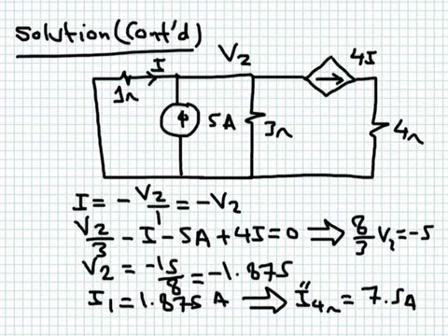Okay, we repeat the circuit analysis. Now we get rid of the voltage source, we shorted it out. We keep the current source. Again, this circuit has only one node. This is one node here. These are all shorted. And the second node is ground. So the easiest way to solve it, please don't treat it as 3 loops. Don't apply loop analysis here, because loop analysis will give you one equation, a second equation, a third equation. Why would you do that when you have only one node here?